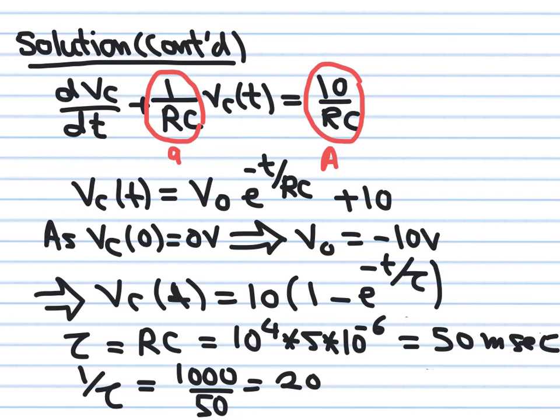So now this is the expression of a capacitor that's charging. Why? Because at time 0, if you put t equal to 0, this becomes 1, you get 1 minus 1, then VC at time 0 is 0, which is fine because we started with 0 initial values. As time goes to infinity, this whole term will approach 0. And then you get 10. So the capacitor voltage really looks something like this. It starts with 0 at time 0, and then it goes up to 10 at infinity. Okay, so it's the expression of a capacitor charging. Okay, this is VC of t.